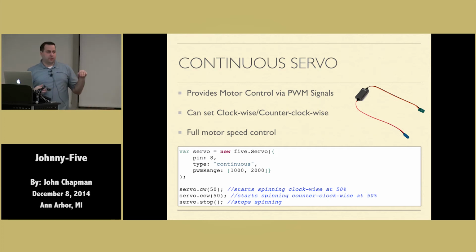Yes. So basically what you do is you say, motor controller, I'm going to send you a signal for 1000 microseconds, and that's going to tell it, okay, I need to set my servo to 0. If I send it 1500, that sets it to 90, right? Because it's at 0 to 180 degrees. So because that sort of logic is in the motor controller, these things get to be a little bit expensive. These particular motor controllers that I'm using cost $10 a piece, right? Versus the DC motors only cost a few dollars. That cost can really add up, but it's adding some kind of smarts for us.